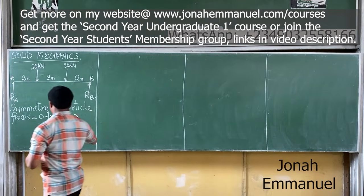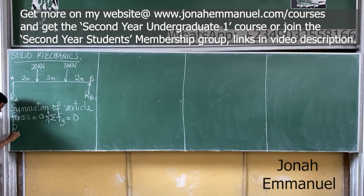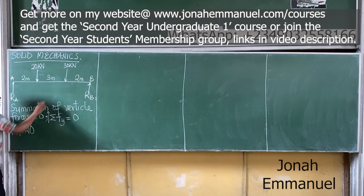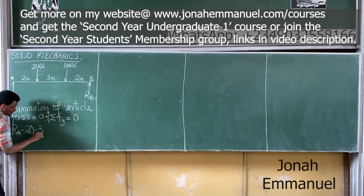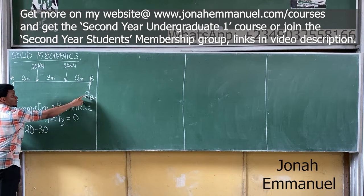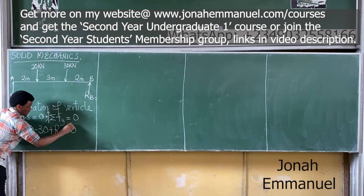So look up, please. Here's how to do this. We have 4 vertical forces. All the ones going upwards should be positive. All the ones coming downwards should be negative. This one is going up, so it becomes RA. This one is coming down, so it becomes minus. What's the value? 20. This one is coming downward, so it becomes negative, minus 30. This one is going up, so it becomes plus RB.